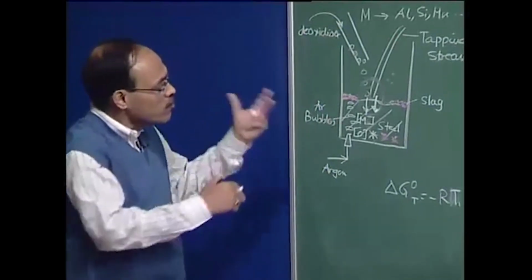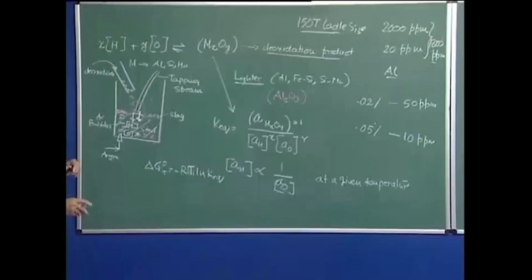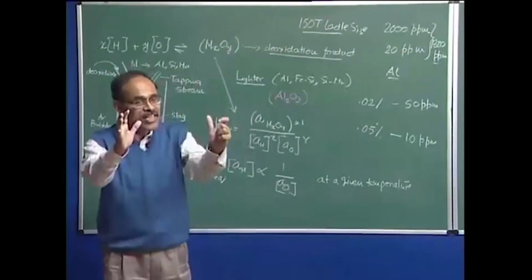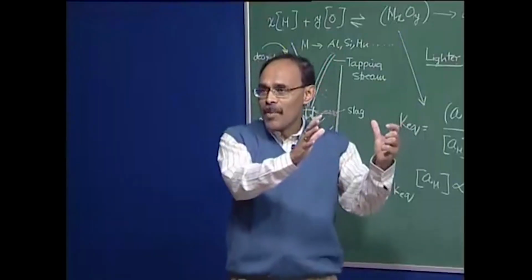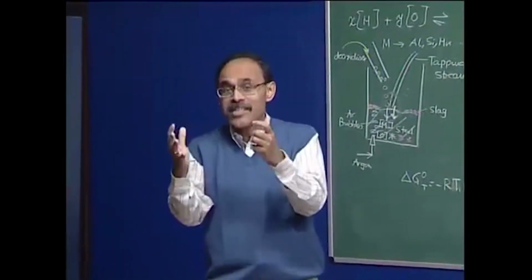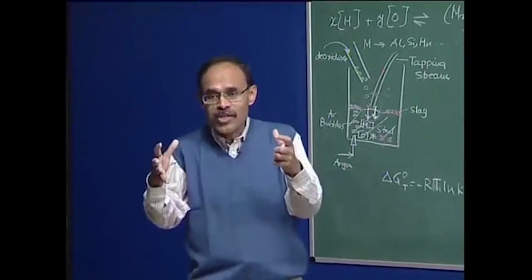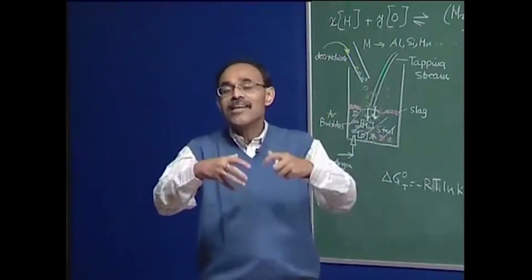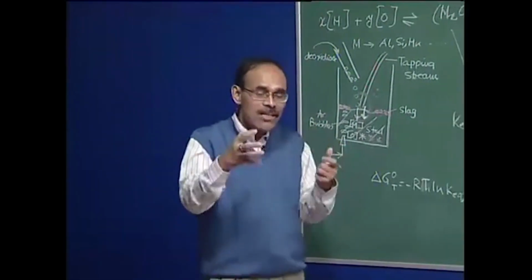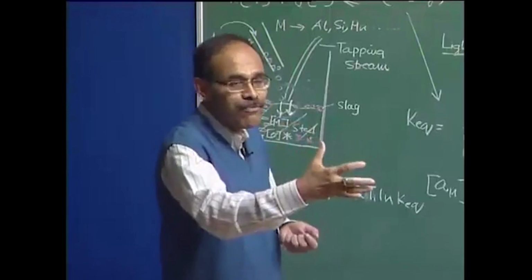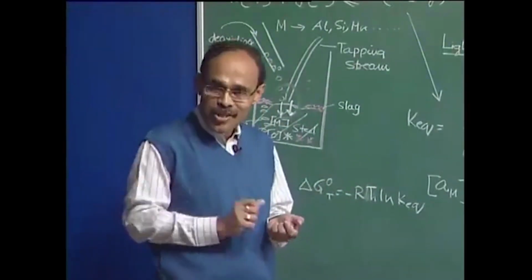lecture and give you an overview of the deoxidation process, I must say that we have primary steelmaking. The bath is rich in oxygen. We have to remove oxygen from the bath, because we know that if it remains, oxygen is going to be evolved during solidification, because solid has less solubility than liquid. So the oxygen present in steel is going to impair the mechanical properties. Before we process steel further, we would like to take out oxygen first.